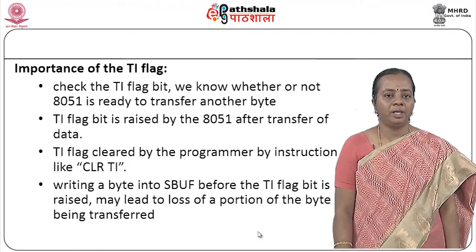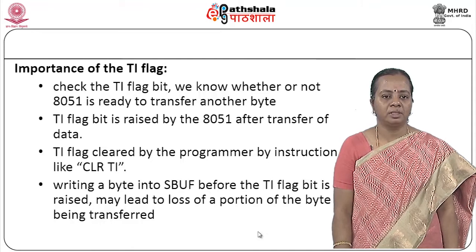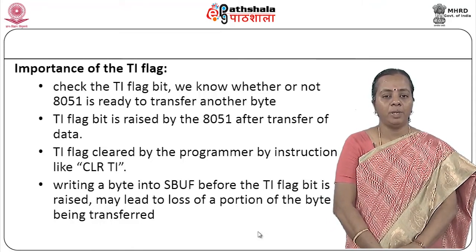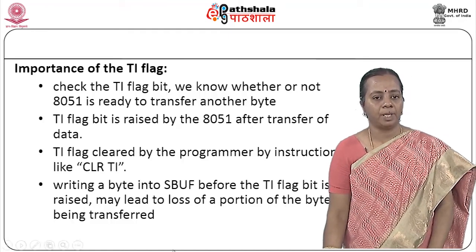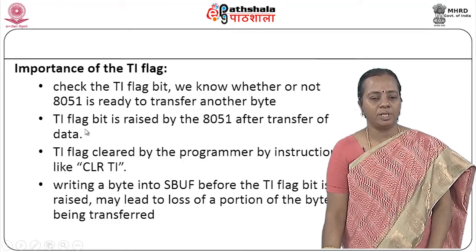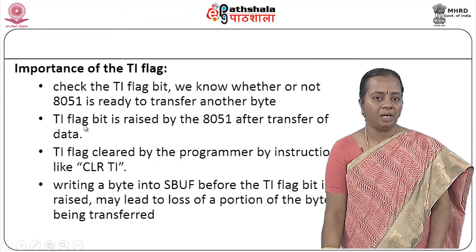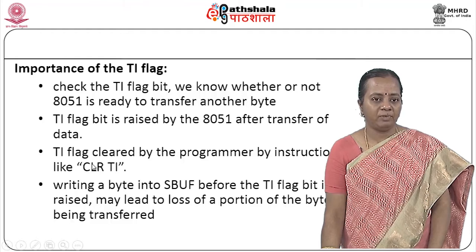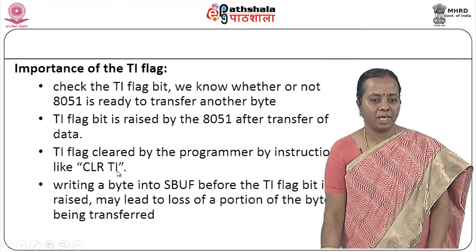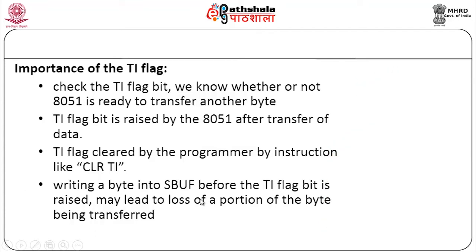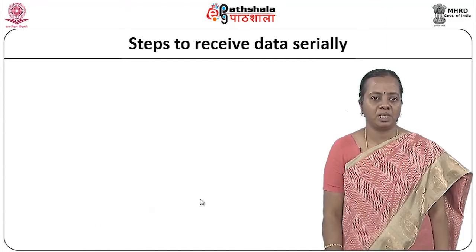The importance of the TI flag is that if it has not been raised, we will not know when the transfer of data is complete. Once it has been set by the hardware, it has to be cleared. Since the data has been sent properly, we clear it again so that we enable the next transmission. So for the smooth conduct of transmission, people look at this TI flag.